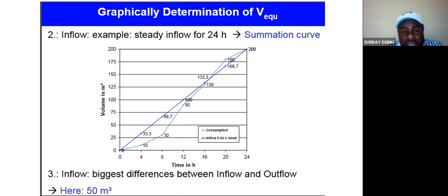What that means is that while the pump is pumping at a higher value, the water is leaving the tank at a lower value, which is the distribution pipe. So that hourly demand is used to size the distribution pipe, while the daily demand is used to size the transmission pipe. Now, what if you are pumping this water, what can you do?